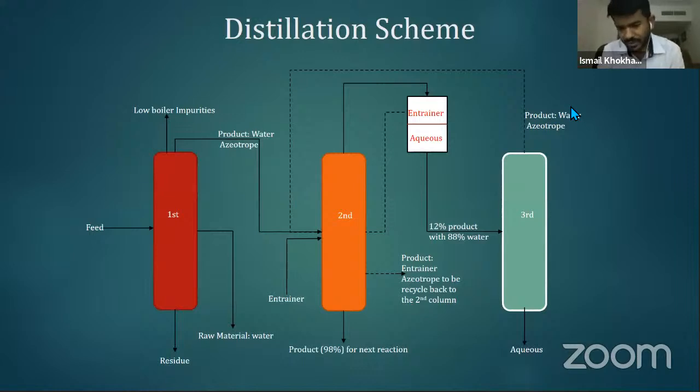Of course, whenever you have a residue coming out, you need to understand the characteristics of what it is, like COD, BOD, TDS, organic matter, and everything, because you need to understand the characteristic of the aqueous as well, because sometimes it may create a difficult situation in the effluent treatment plant. The effluent treatment plant is the heart of any chemical unit, because if the ETP gets stuck, then the entire plant needs to be shut down, because ETP cannot handle a particular effluent above a particular load.